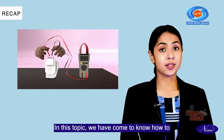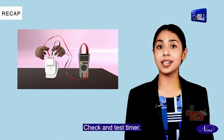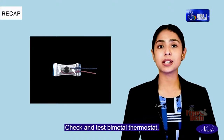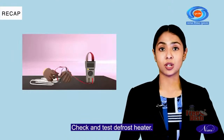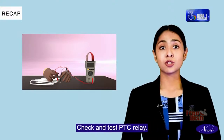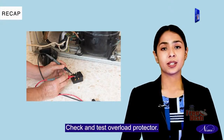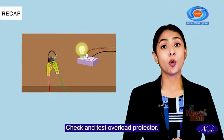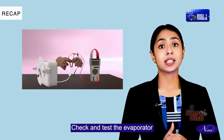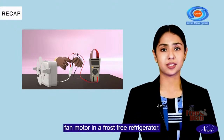Recap. In this topic, we have come to know how to check and test timer, check and test bimetal thermostat, check and test defrost heater, check and test PTC relay, check and test overload protector, and check and test the evaporator fan motor in a frost-free refrigerator.